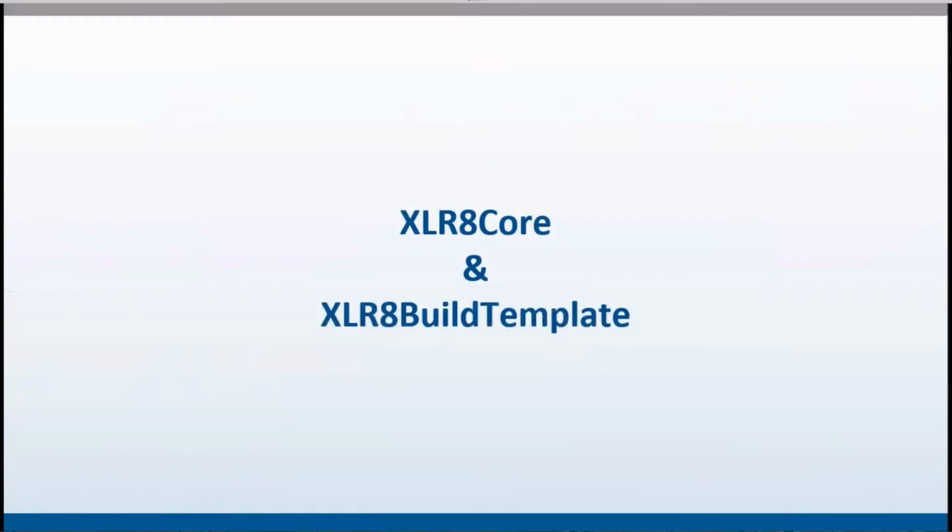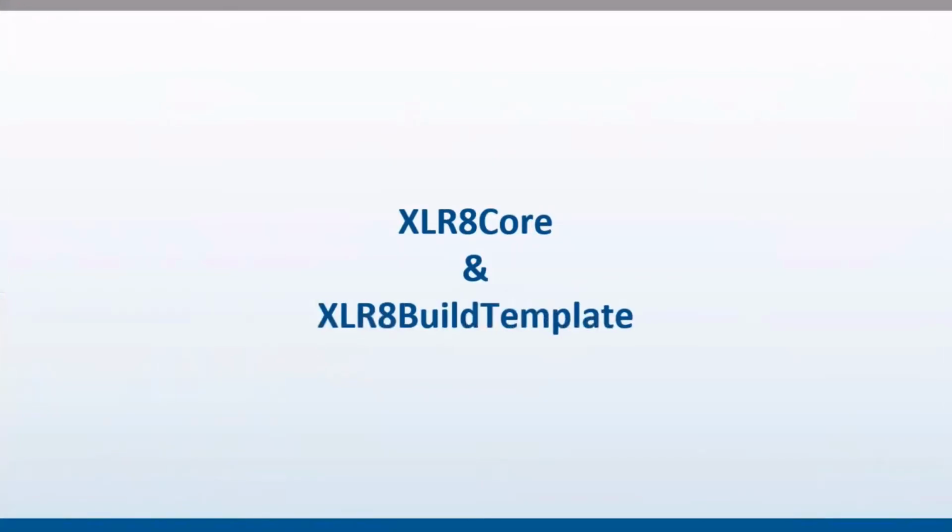So there's two core libraries that are provided for OpenXLR8 that provide the foundation for running OpenXLR8 Flow: XLR8Core and XLR8BuildTemplate. The XLR8Core contains all the base libraries, scripts, source files that are needed to compile the entire FPGA design in Quartus. And then the build template provides a framework for the users to add their own custom logic. It's a template that you modify a few files here and there, and that allows you to bring in your own logic.